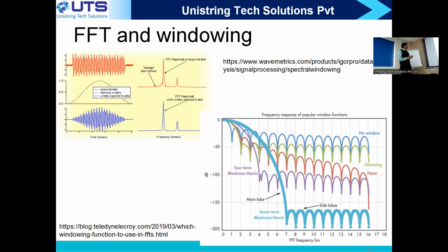So in most applications where you use FFT, not only radar, you never use the FFT with a rectangular window. Rectangular window means no window. You directly take the samples as a discrete cut. You will apply some window function and then do it. And now the actual thing to understand is that there is a trade-off between two things. In engineering, you always design with trade-offs. You have different options, and which option you choose depends upon where you can trade the properties of the system.